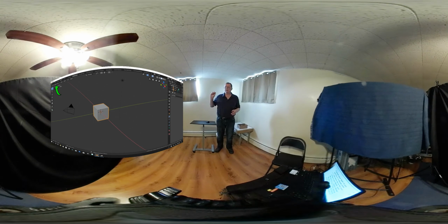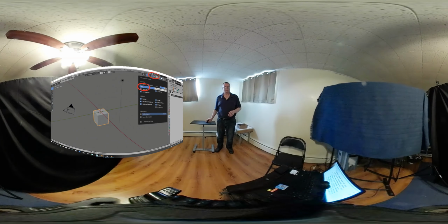So, I mentioned that this is in what's called edit mode, because you'll see that on the top of it, it currently says edit mode. We need to change that to object mode, and so if you click on that and drop it down, it'll give you object mode as an option. It's funny because we lost our grid again when we went into modeling mode here. And the same thing happened to the reference video that I used.